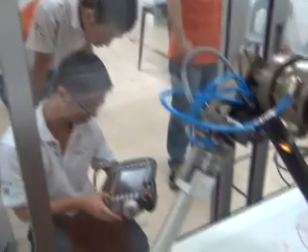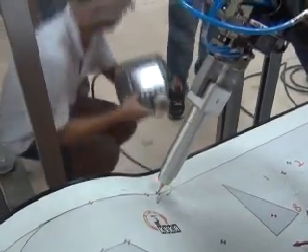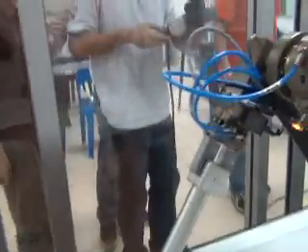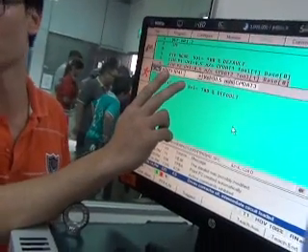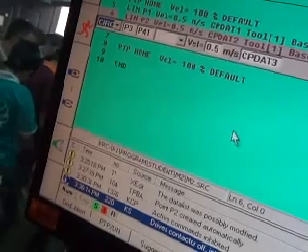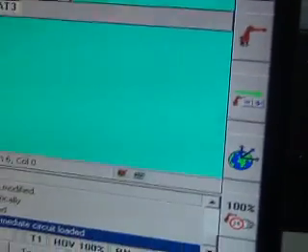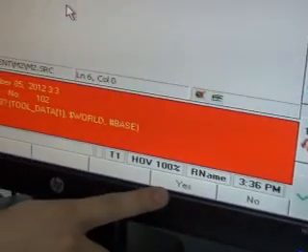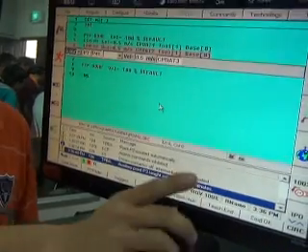Choose a circular motion. And you can see from here, we're having 2 points, right? P3 and P41. P3 corresponding to auxiliary point. P41 corresponding to end point. So now you have placed the robot at the auxiliary point, so you press this, teach auxiliary point. Yes. Don't do anything, proceed with the end point.